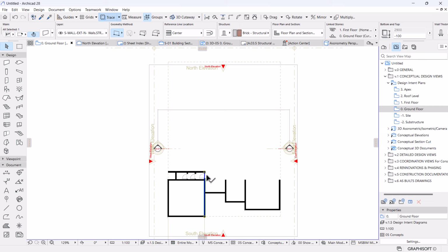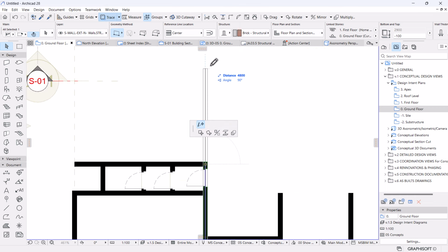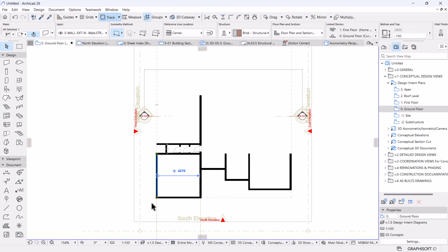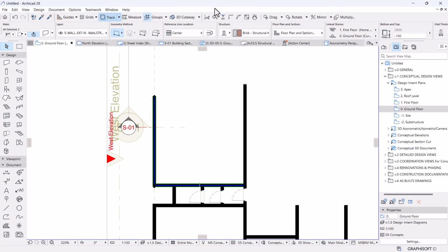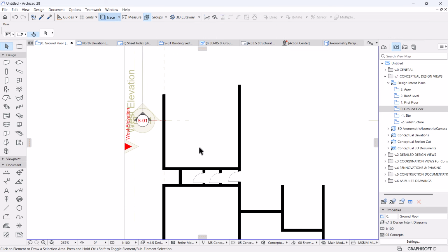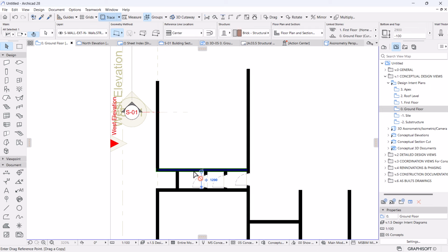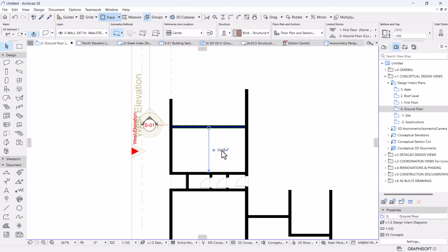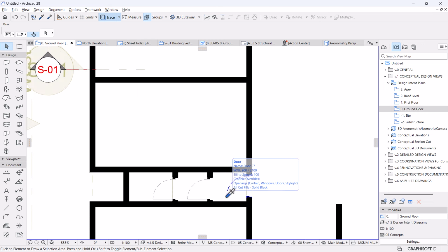So this wall will continue to stretch all the way like that, because I'm going to have the staff room here, which is going to be on the same footprint or the same position with the garage. Okay, so I'm going to chamfer that. Then this will be roughly Control Shift D. I'm going to make a copy of this wall to enclose the staff room, which is going to be 4 meters, 3.7. I think it's too much. Let's make it 3.5. Then we'll create a door here.